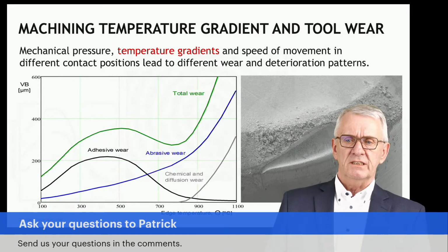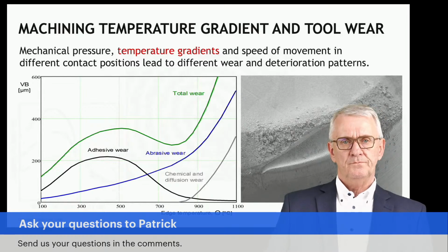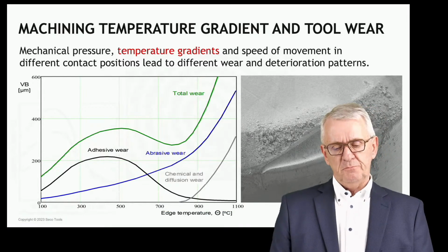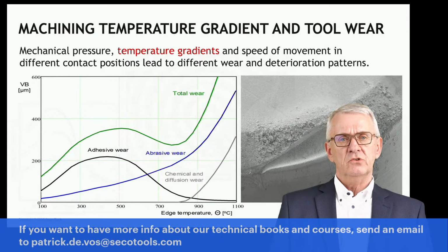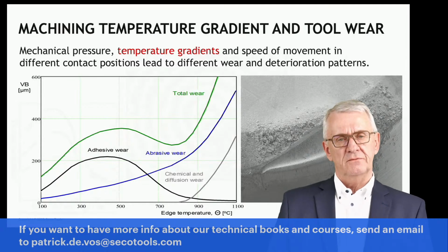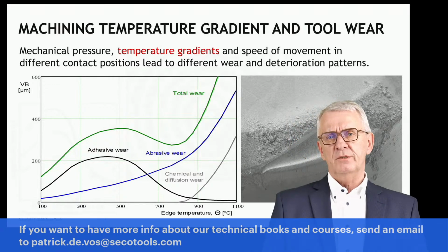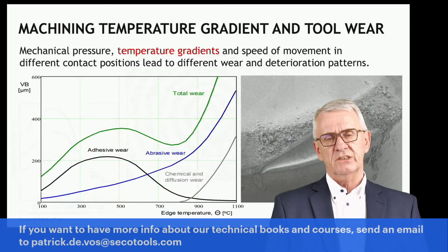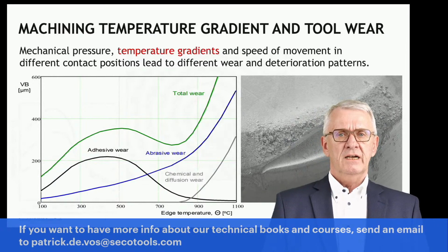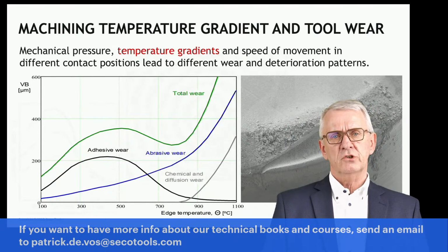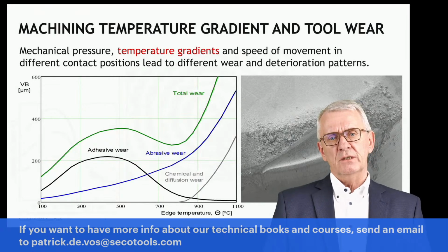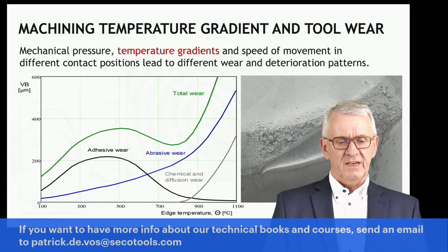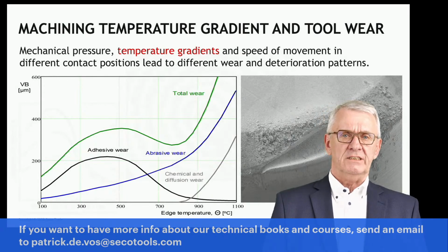that when the temperature is rather, let's say, low, you have a certain speed with which the wear develops. And as you start to increase temperatures, you see adhesive wear patterns and abrasive wear patterns, and I hope you are a bit familiar with those things. We already spent attention to this at previous Getting Technical events. You can always watch it back there if you are not so familiar with these types of things. But adhesive wear increases rather rapidly when the temperature increases. Abrasive wear also, but less.